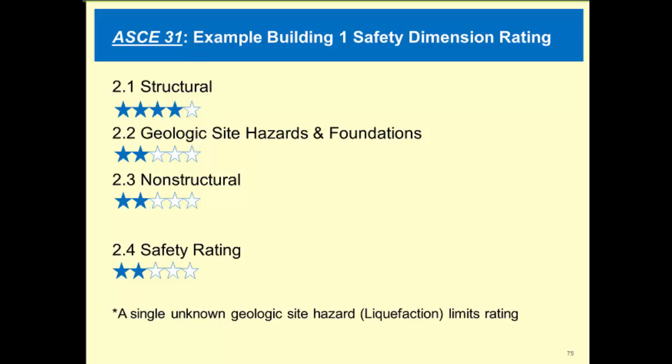So if you're looking at a big portfolio of buildings and you had a couple buildings that had, like we said, stair details that were non-compliant, if you're not looking to increase that rating and you're just looking at the very basic rating, you can stop right there. Just look at that non-structural checklist item. You have a single non-compliant, and you don't have to pore through the rest of the checklists. So that's more of a time-saving thing. But for a USRC rating, you do need to go through that whole process.